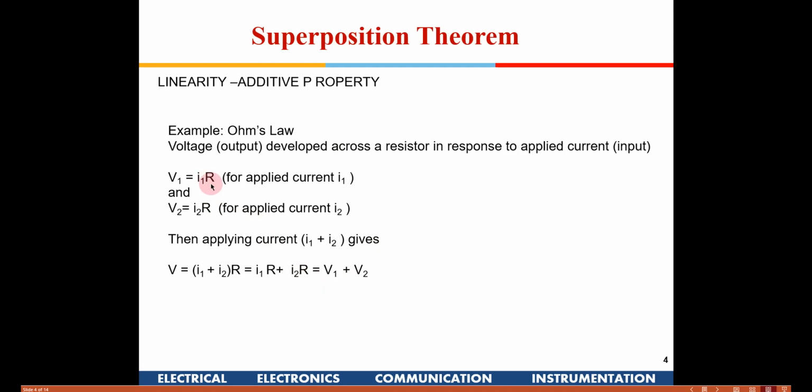All the elements in this circuit have to be linear. Resistance is a linear element. Similarly, you can have inductors, capacitors or transformers, which will also be linear. Whereas diodes, transistors, MOSFETs and those things are not linear. Those components are not linear, so we cannot use the superposition theorem for them. Towards the end of the lecture, I will show you a video and explain further how diodes and such cannot be used for superposition theorem analysis.